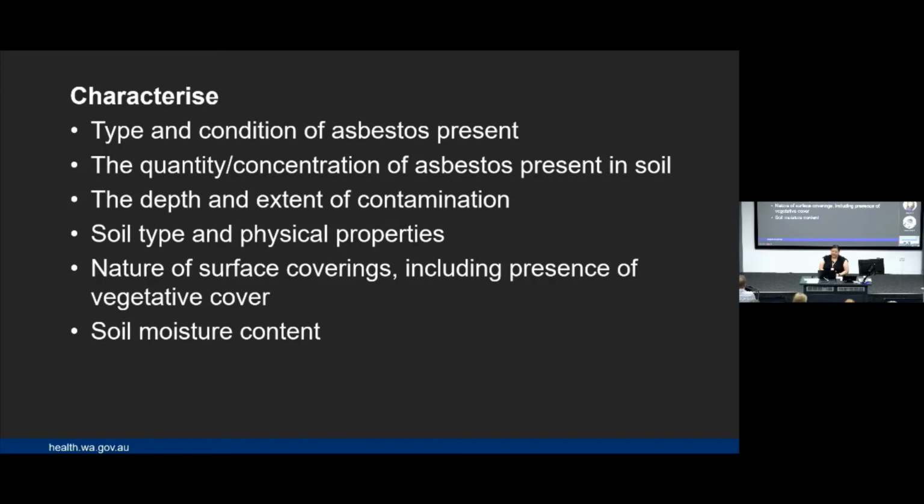The extent and the depth of the contamination, what are the soil types and physical characteristics, what surface coverings are there at the site, and if you've got vegetative cover, you've got to deal with it. So I've heard many times that we had lots of vegetative cover, so we couldn't do a walkover. That's fine, but you can still test pit. So you can remove some of the vegetation cover, do some test pits, and look at is there any actual contamination if we think there's sort of waste fill here or whatever.